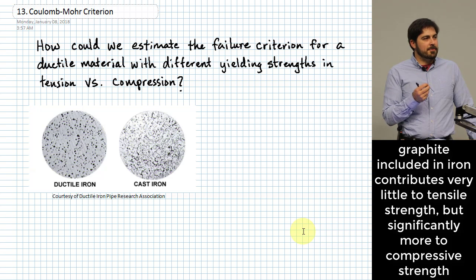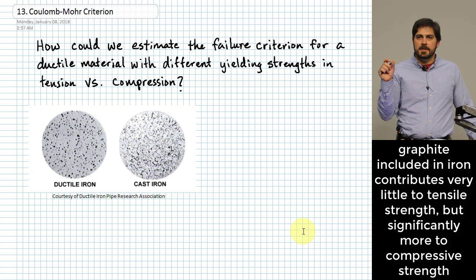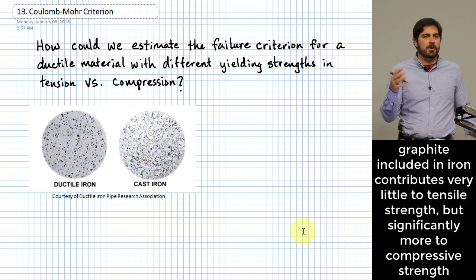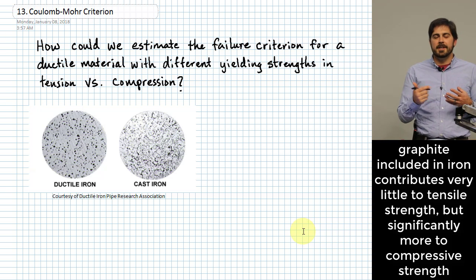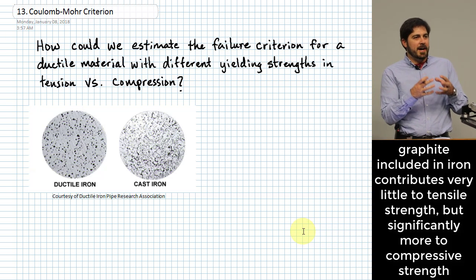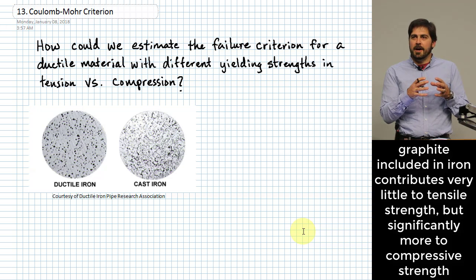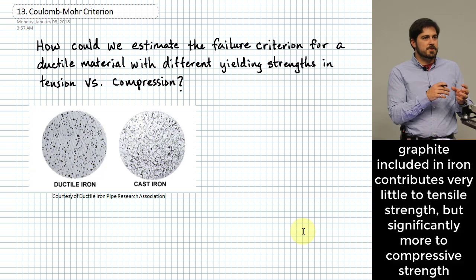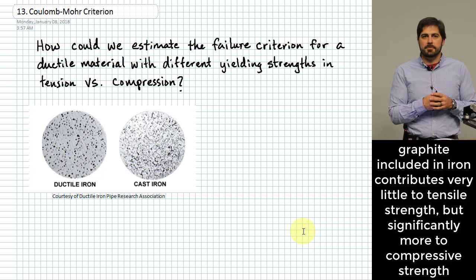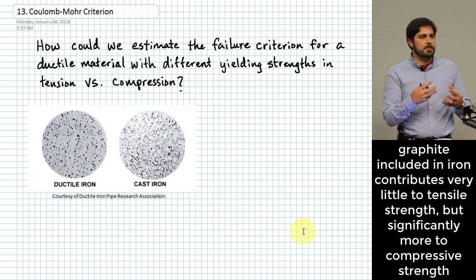The thing is, graphite doesn't have nearly the strength that the iron itself has. And what you have is what they call a matrix. Think of it like a Swiss cheese of iron that goes around a bunch of inclusions in the material. So it's basically like these little bits of graphite are all mixed in with the material.